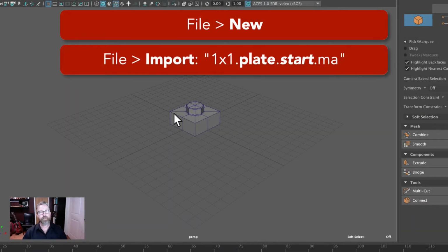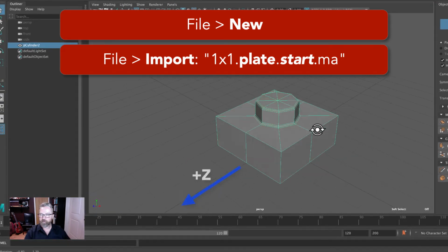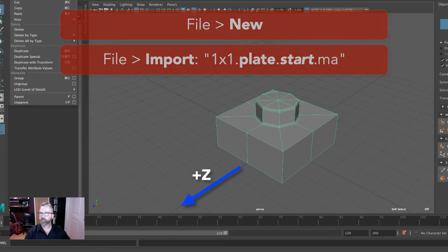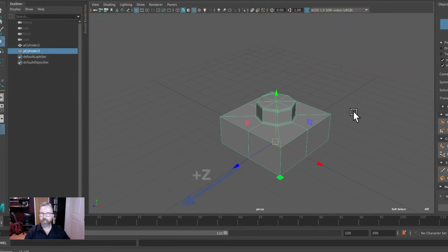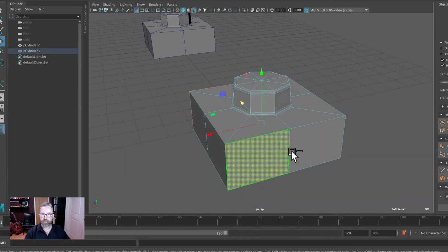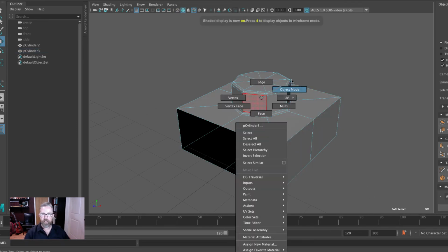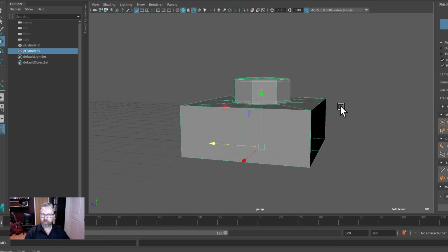Let's use a variation of the last technique that we just learned to create a large plate. Let's say, for instance, an 8x8. We'll begin with the process that is familiar to you. I've got Z forward, and we'll make a duplicate, and we'll slide it out. I'll hit the F key, and we'll just make it a hollow see-through, right? Selecting those, we can hit the 4 key, and we'll hit delete. And so we've got that piece that we can see through.